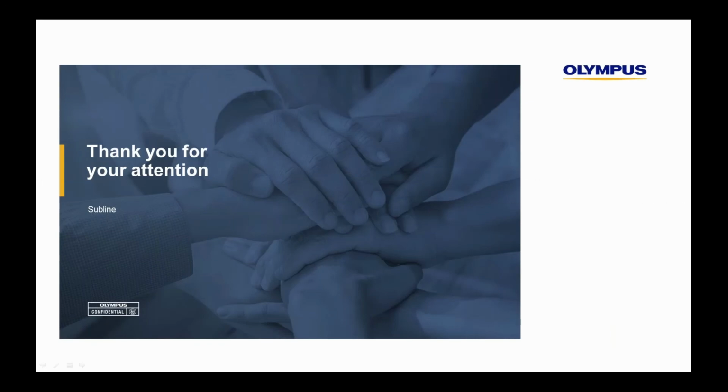You've got the slightly wider field of view now, which means that you can use that single screen option if you need. When you get to a defect, you've got the ability to understand some of the environment before carrying out that measurement. So it's something we've introduced called spot ranging, which gives you a 3D plot on top of a surface. So if you're looking at, for example, a small dip or a dent, you can place this 5-point circular target on top. It gives you some indication of how far away all of these different points are from the scope itself, which gives you an understanding of what the surface looks like.